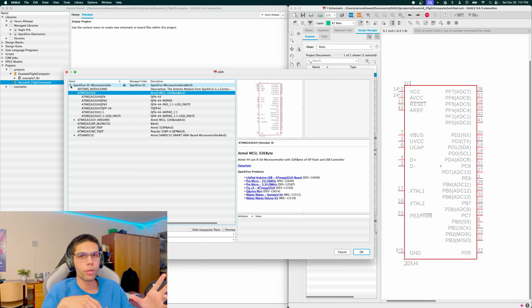So just by using an accelerometer, you can tell where your rocket is right now. And by using gyroscopes, the sensors that measure the angular acceleration, how fast your angular velocity is changing, we can see how our rocket is rotating. You can do the same integration twice with time to get the angular displacement: how much did our rocket rotate in total? That way you get your attitude.